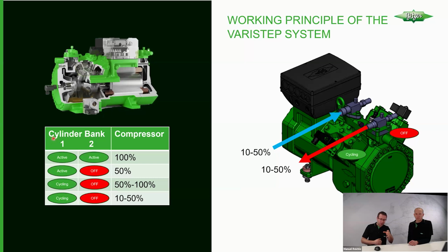Because if everything is constantly at 10%, the oil will get too hot, because there's not enough suction gas flow coming to cool it down. The discharge gas temperature can exceed 284, and we will not see it. Therefore, the IQ module has a special function to monitor this situation. After a certain time, depending on whether I operated the compressor at 100% before, or at 30%, what the situation was before, the time is always different for how long I can run it at 10%.